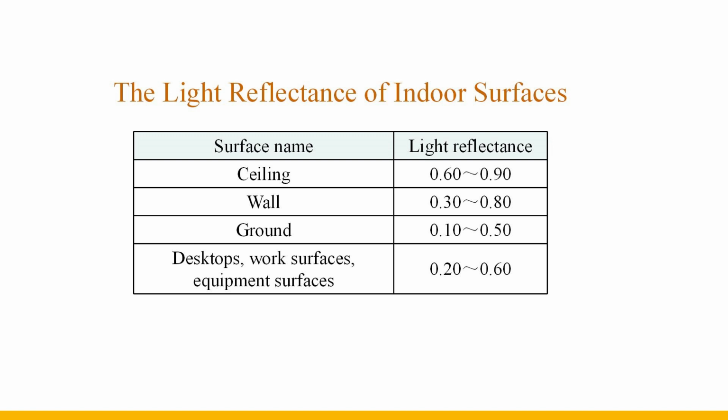Therefore, the place where the color needs to be identified should use lighting materials that do not change the spatial distribution of natural light. In places with special requirements such as museums and art galleries, in order to protect cultural relics and exhibits from damage, it is necessary to eliminate ultraviolet radiation, limit the value of natural light and total exposure time, and limit the entry of direct sunlight.